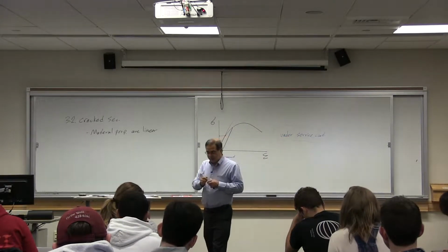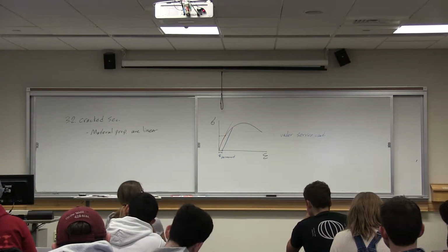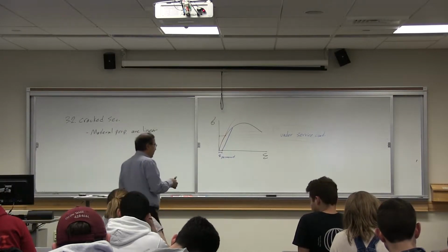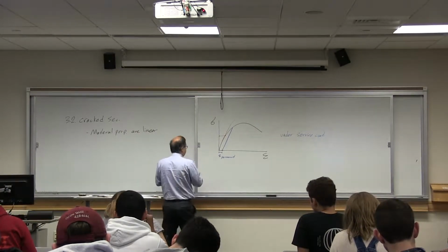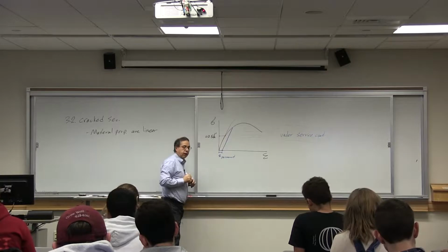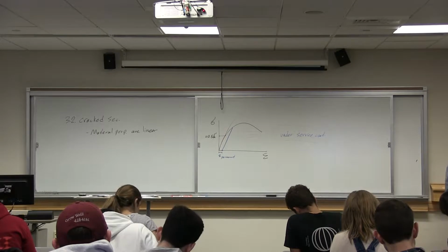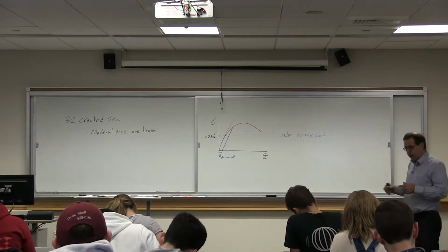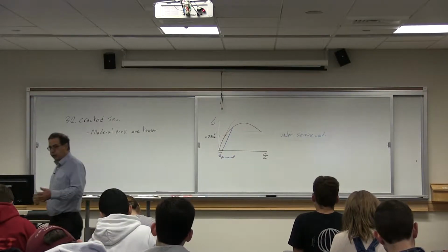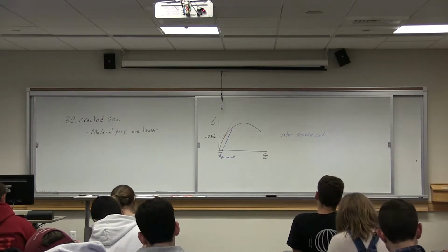So when you have everyday loading, you don't want to stress the concrete beyond the approximate linear range. This linear range is not a perfect number, in the neighborhood of 0.5 f'c. A little bit more, a little bit less, depending on who is looking at the problem and what criteria they are imposing. If you look at some books, they say 0.4, 0.45, 0.5, or even slightly larger. But in the neighborhood of 1/2 of f'c.